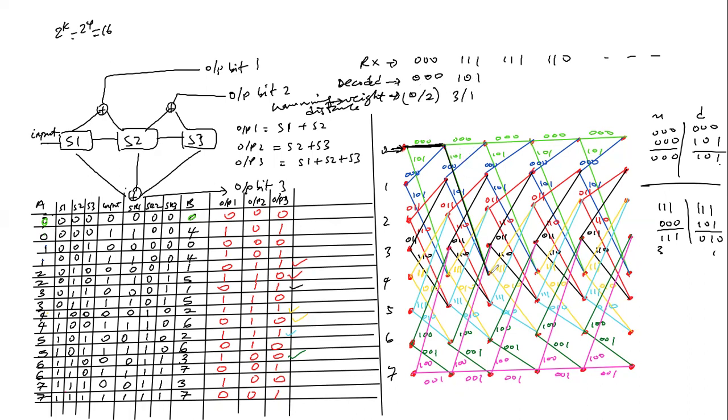From this point, we now have two possibilities as well, but we received 111, 111, upward and downward. Going upward is 111 here, 111. Then going downward is 010, 010. Once we take the Hamming distance, this is 000, then this is 101. So that's 0 over 2.